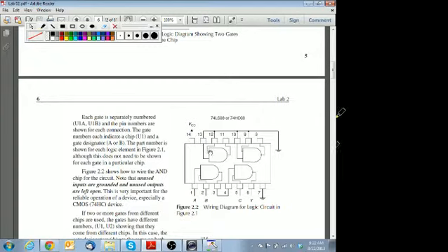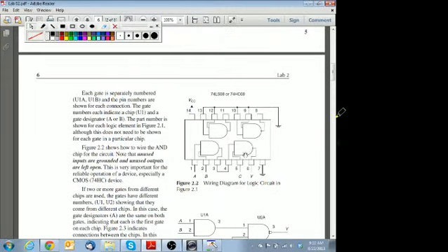And the reason you want to tie the inputs to ground is because those are very high impedance inputs, and typically they're like a MOS capacitor, and so they can have voltage induced on them. So the outputs can flip and flop around, and that'll cause noise and things on the board. So you want to ground them, or you could pull them high through a resistor, preferably. But the easiest thing to do is just to ground them.